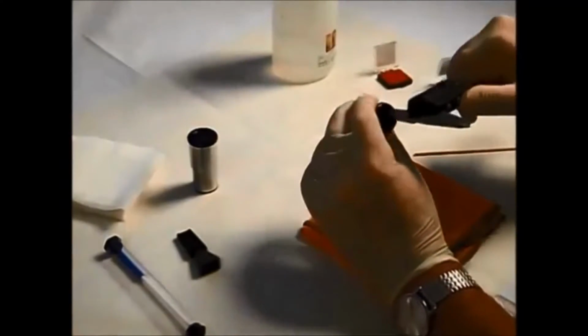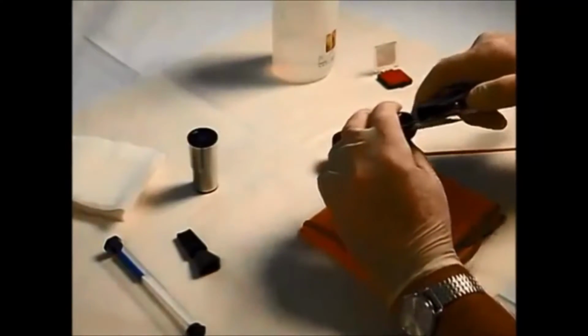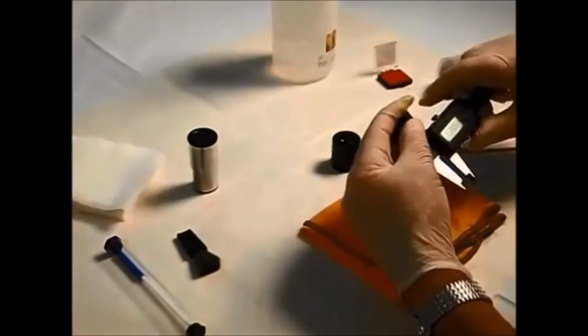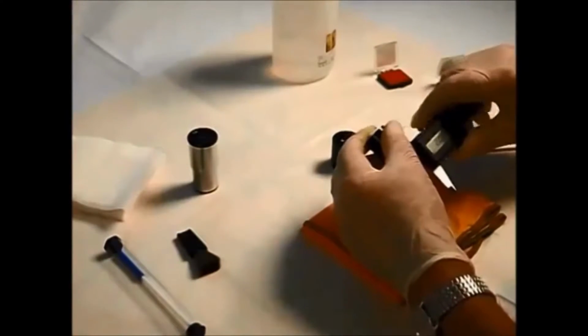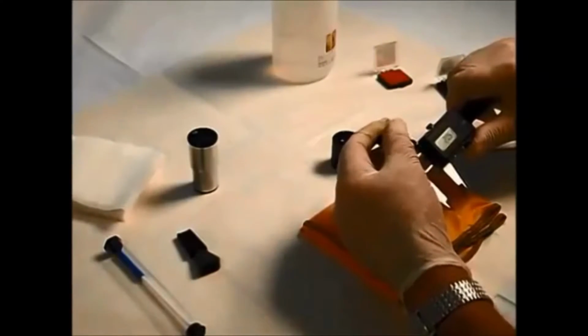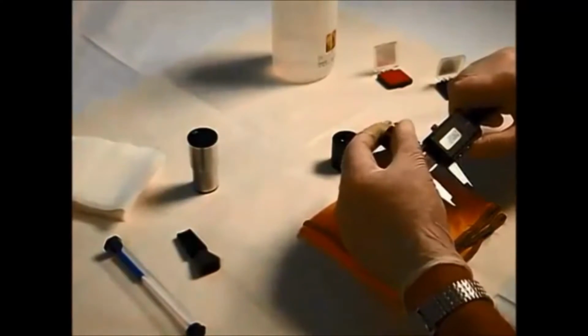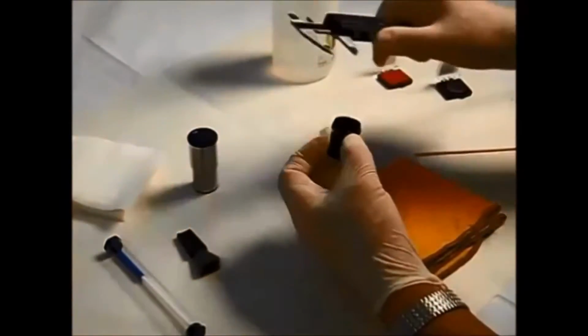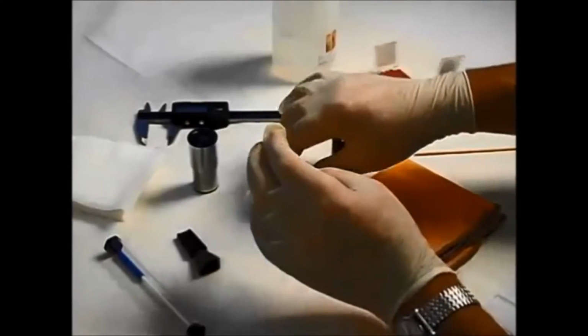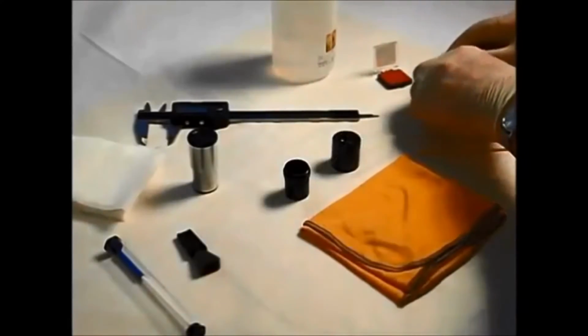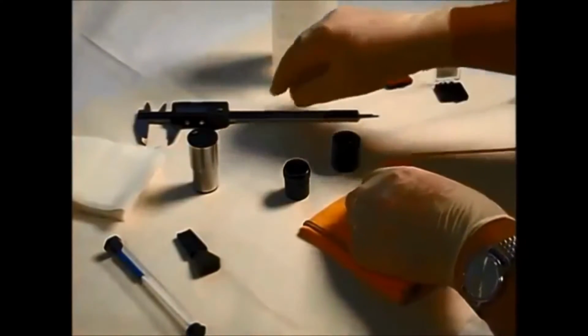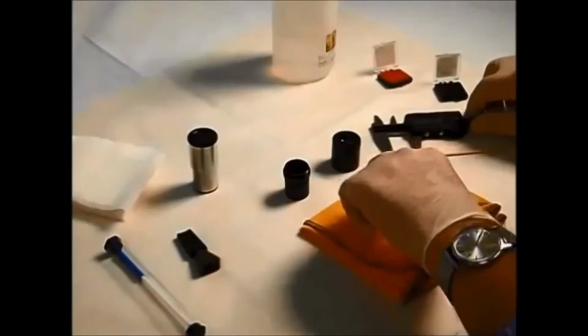So again, zeroing the micrometer. Let's work inside there, working on the right side. Now this is reading just a fraction over 20.5. It could be a little bit bigger. I think we could possibly get a 20.5, but I think maybe a 20mm would fit in there as well. So I have one here which is actually 20.5 to go into a 20.9 fitting.